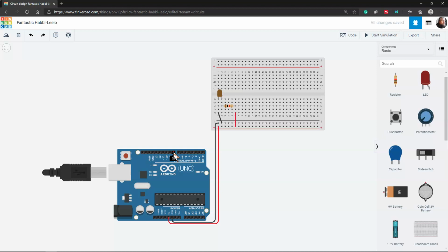So this means through that pin, we can control to say, hey, that pin has no power, so it's 0, or it has full power, which is basically that 5 volts that we're working with. And so we can control that. So in the code, we can tell the controller, hey, on that pin, put no power, or put more power, and so forth. So what we want to begin with is, we don't need these power pins here. We're not using anything for the power from the Arduino. That could be used for other things if it needs, say, motors or other stuff, basic motors.